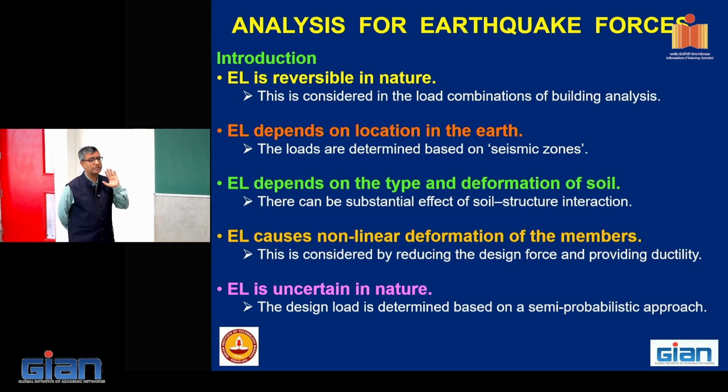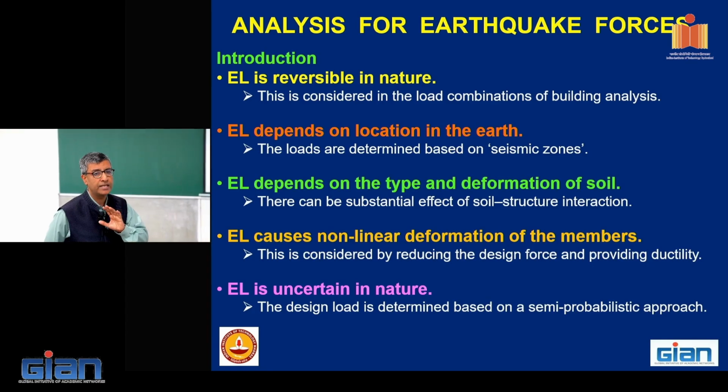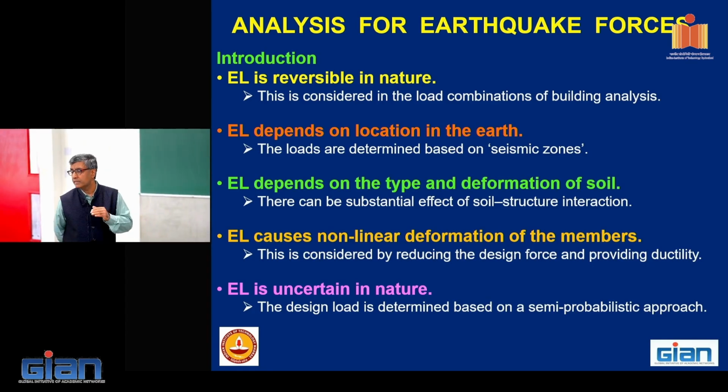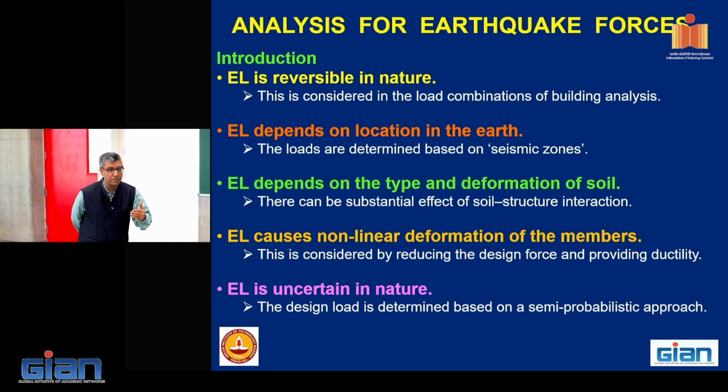Okay, under the design wind force, the structure will stay elastic because we can afford to do that. Whereas for earthquake, the forces are so high that even for conventional buildings, we cannot afford to have the members stay elastic. Then we have to design it for nonlinear behavior because otherwise it will be very costly. Okay. And earthquake is also uncertain, and hence this probabilistic approach comes in earthquake also.